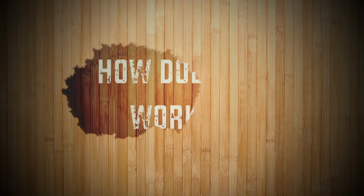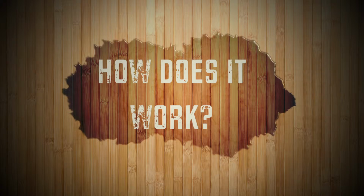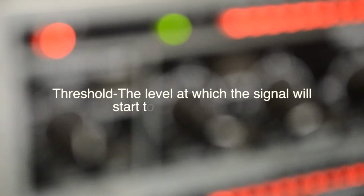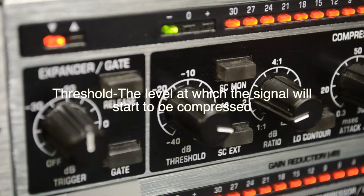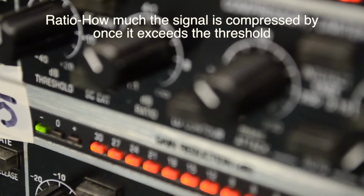Compression is achieved by squashing the peaks of a sound wave in order to reduce the amplitude. This is done using two main parameters. The threshold determines the level at which the compressor will start to compress the signal. The ratio controls how much the signal is compressed by once it exceeds the threshold.